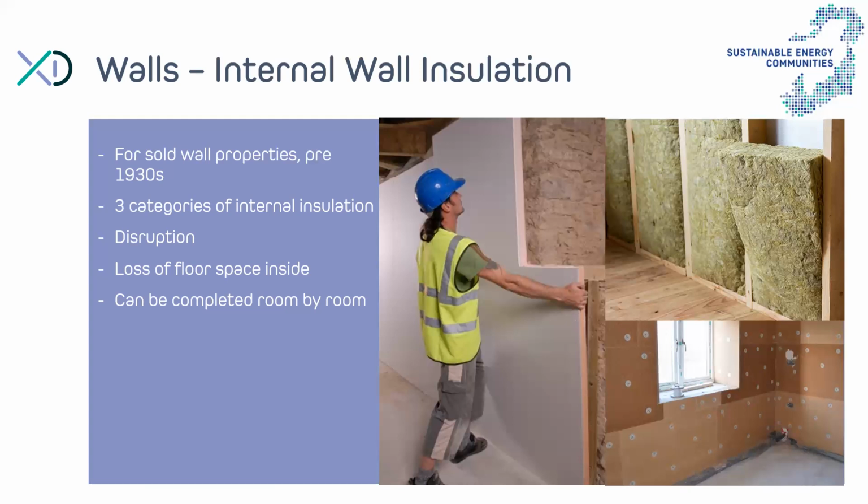So I think that covers internal wall insulation. So I guess the downsides of internal wall insulation are that it takes space internally, and also it's very disruptive. Obviously, you typically would have to move out of the rooms where it's been done, and sometimes move out of the house entirely for a period of time. And it's not as expensive as external wall insulation, but it's still quite expensive compared to, let's say, standard cavity wall insulation. But in some cases, you have no choice.